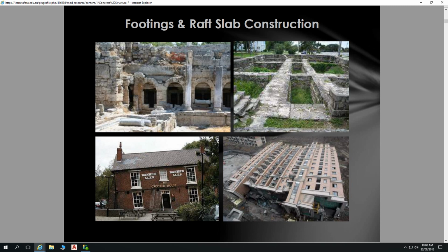And so that's going to be the way with our concrete slabs as well. So we'll form up beams, and the way that we design our raft slabs typically, I'm talking typical examples here, is to move around with the soil and carry the weight of the building as it moves around. So we want that raft slab to be able to do this. There is always some difference of load throughout that slab, earth pushing up underneath it or subsiding. That will cause some elements of that slab to be in compression, some elements of that slab to be in tension. Our steel is to resist those tensile forces.